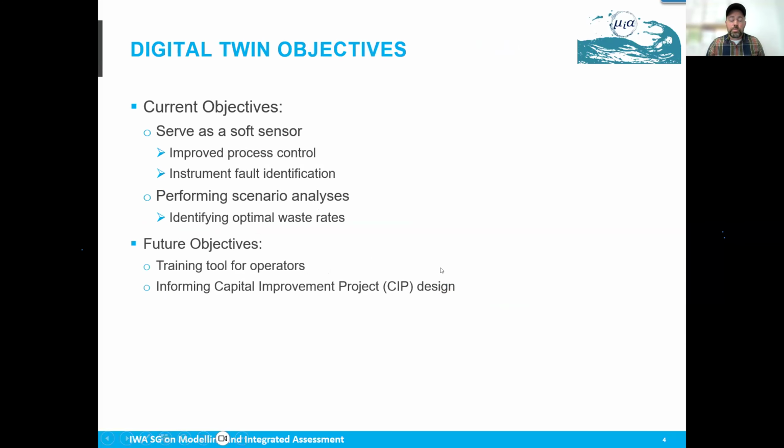As you can see, the Nansemond Treatment Plant is going to be a pretty complicated plant. It's going to have pDNA in the biological process. It's going to have this full-scale indirect potable reuse facility. And that IPR facility has an instantaneous total inorganic nitrogen limit of 5 milligrams per liter. If we exceed that 5 milligrams per liter at any time, we have to suspend recharge of the aquifer.